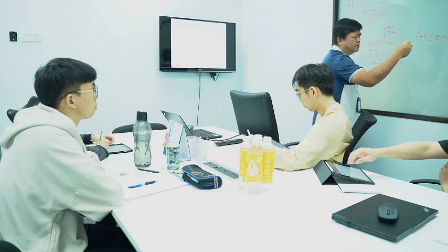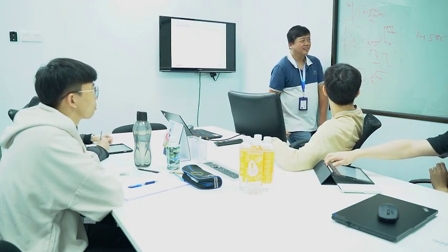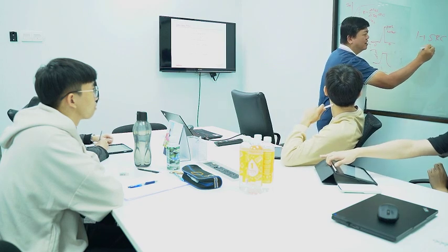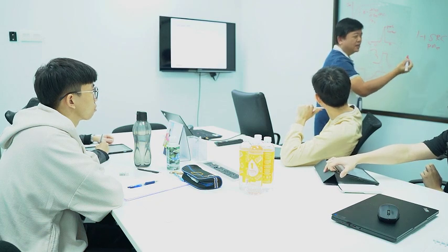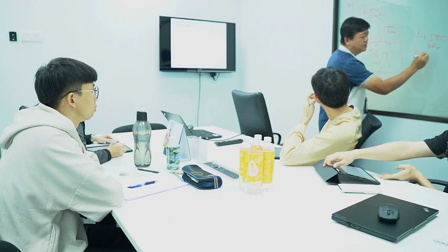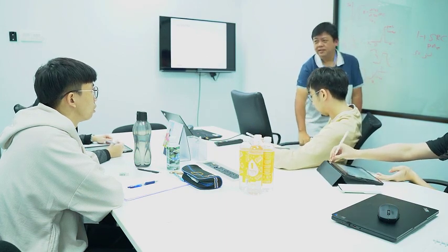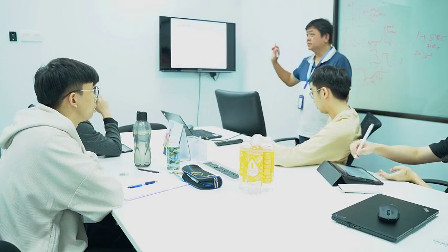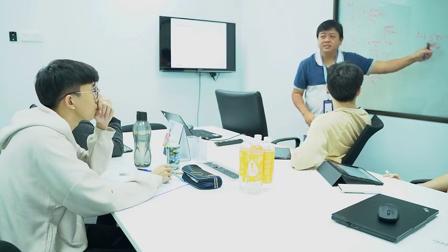I always remember 1 plus SRC. Remember, this is called one pole. Actually, S is your variable frequency. S equals j omega. So RC is a constant, defined by your R and C in your circuit. S actually is your variable. This will tell you whether, at this frequency, it can be filtered out by this RC or not. S is the variable.